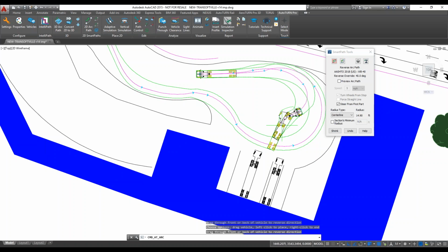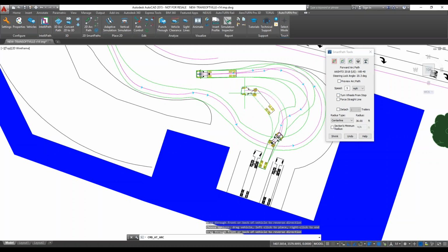So we can switch and use one or the other reverse method to accomplish this type of maneuvers and generate sections. Let's say I managed to park it there and it's in good track to do that. Once I move forward, you'll see the option is checked by default. It's because, well, the first section after a reverse section, the vehicle is coming from a complete stop and then moving forward. So it'll be checked, so be aware. If you're, again, just trying to exit, you may want to uncheck it for the next section so that you have that spiral portion incorporated into your path.